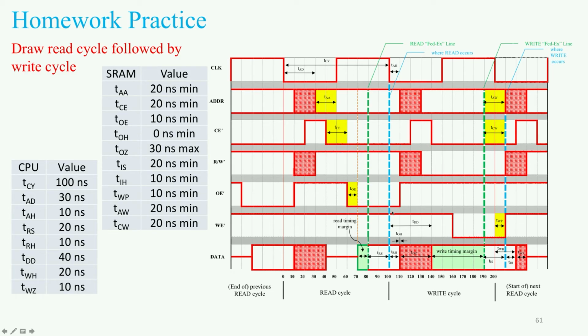With output enable, when the clock went low, output enable flips up to high, and then that just stays at a high state because even when the clock flips high here, this bit is down, which means you're not actually wanting to output anything from the SRAM, so that bit just stays constant throughout the rest of this question.